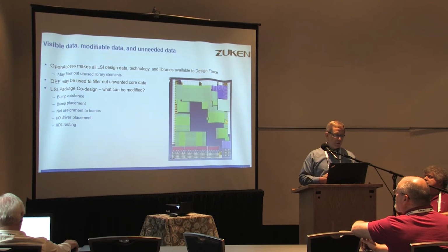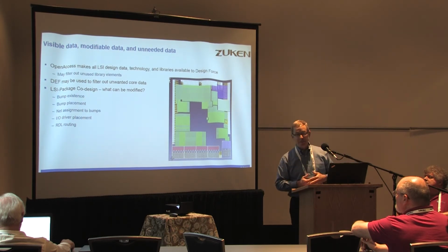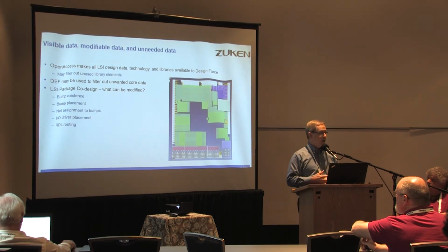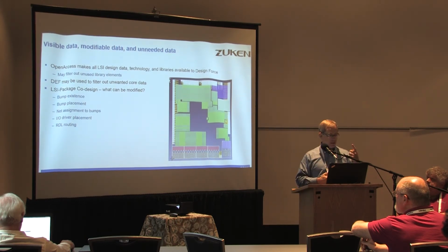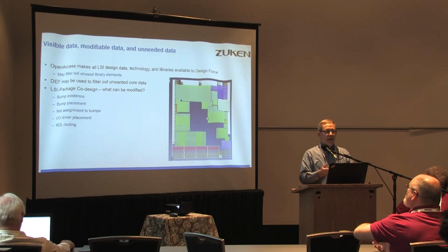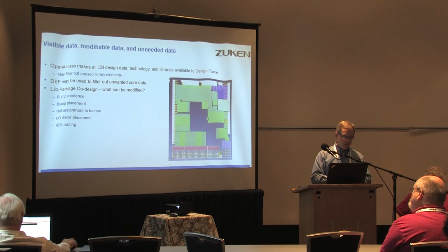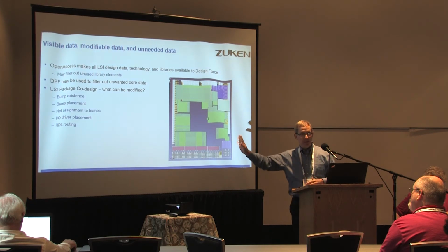Okay, what's visible, what's modifiable, and what's not needed data? Typically in a chip package board co-design flow, you don't need the core. And so we will strip out LEF library elements that are not referenced in the design, because there are some very huge LEF definitions out there, and that will bog down any system. Some of the LEF libraries are huge. So we'll strip out library elements that we don't use, and DEF, as I mentioned earlier, can be used to filter out unwanted core data. And so it makes for a very lightweight implementation.